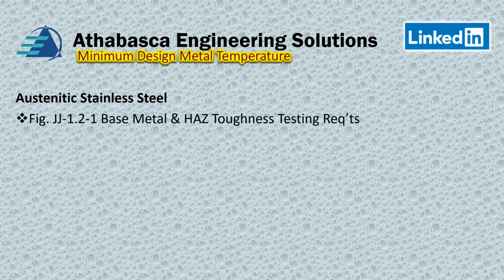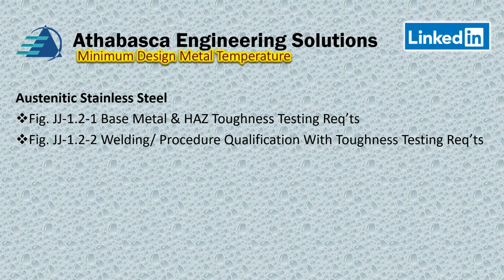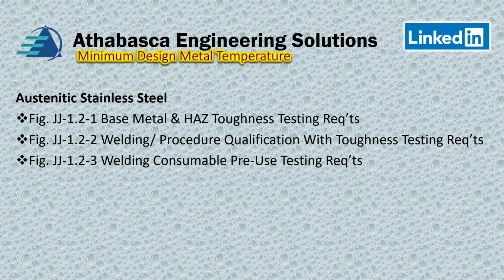And so what they do is they have the base metal and the HAZ, heat affected zone, and they group those up as one group, okay? And they have a set of procedures for those in terms of a chart. And they also have a welding procedure qualification and a toughness requirement. So you can see how procedure, -2 is a separate chart. And then another chart that's separate is the consumable, because it's important to get the consumables right.